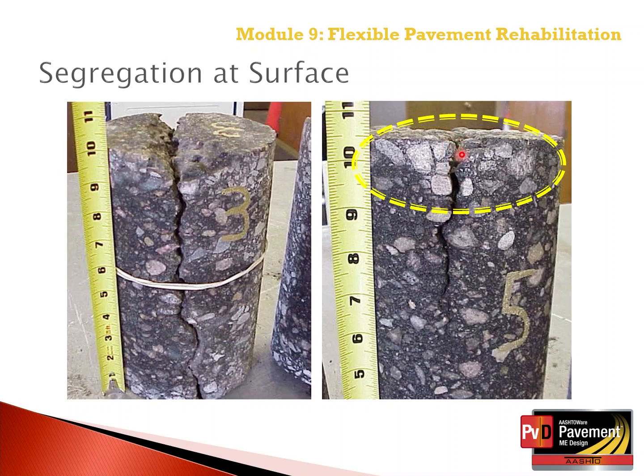So from a surface evaluation standpoint, both of these would be rated as severe cracks, and any cracks from the visual distress survey would reflect through an asphalt overlay in a very short time period. But the rehabilitation design strategy should be different and not the same.